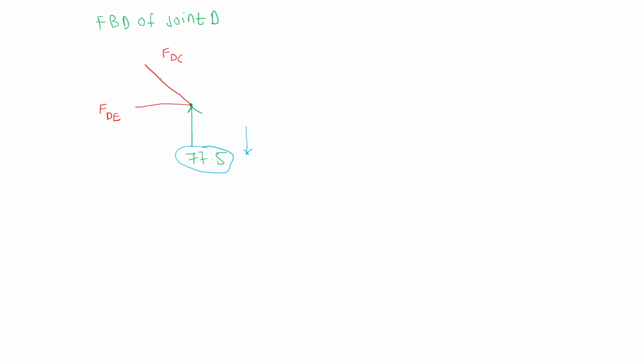After resolution, DE cannot produce it because DE is perfectly horizontal, there is no resolution. So the other component I will show like this. So FDC, again this angle is 60 degree, FDC cos 60, and here FDC sin 60.